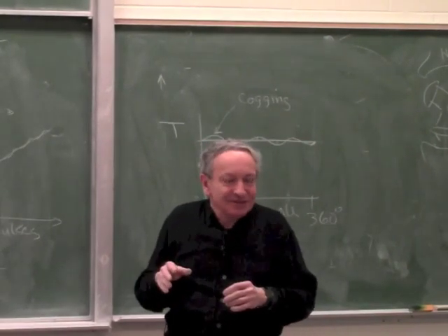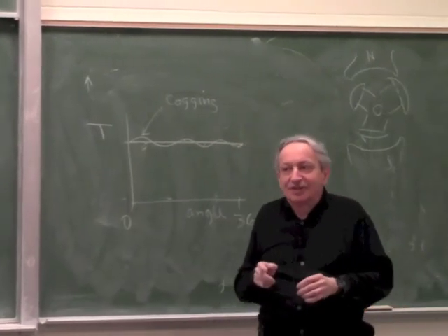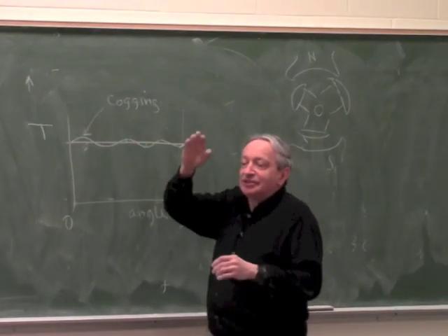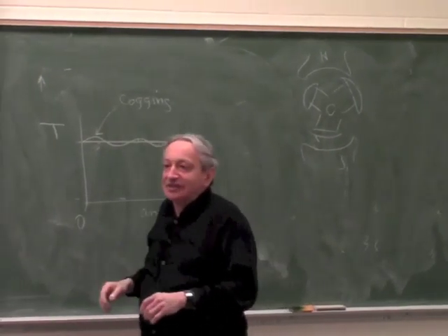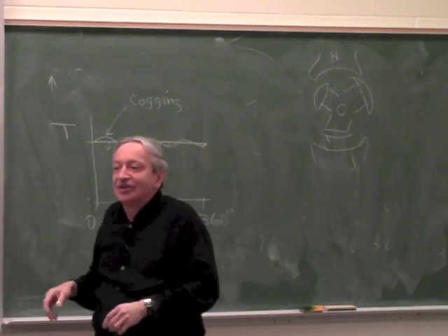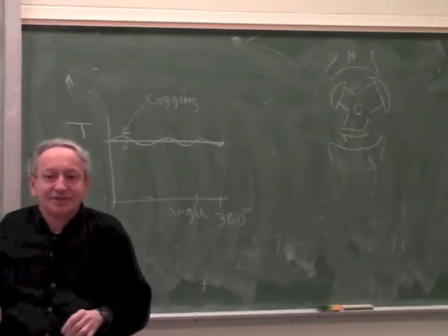Okay? So because of that, the motors which are designed for servo systems try to minimize this. And somewhere at the bottom of the spec sheet it says cogging torque 1% or 2% or 3%. In an industrial motor it's never specified because nobody cares.